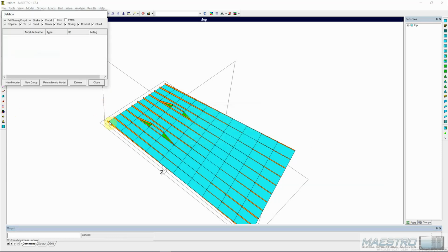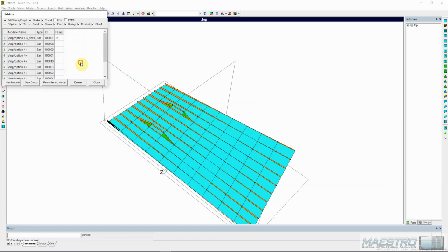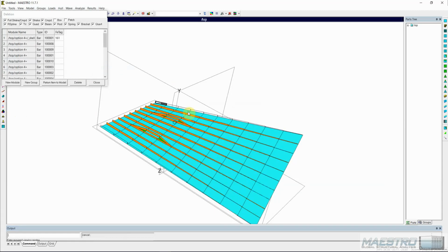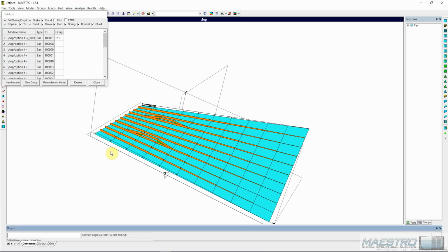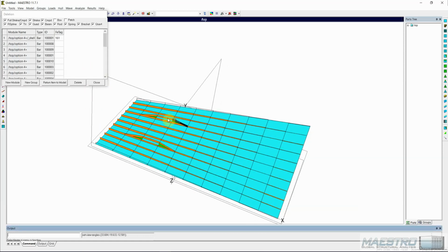It's always a good idea to renumber the FE tags when you import a polygon mesh file or the Maestro neutral file for the beams. And now when we do the exact same operation, you can see we only get the beam traces that we were interested in. And then we can go ahead and add those remaining individual beam elements to delete.